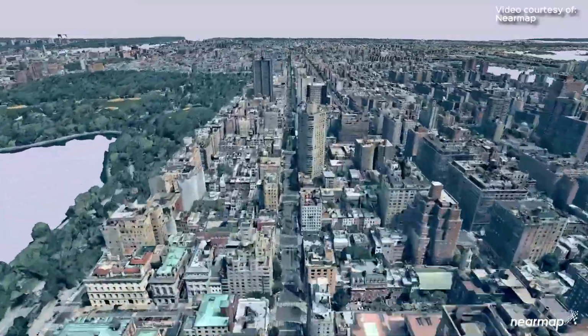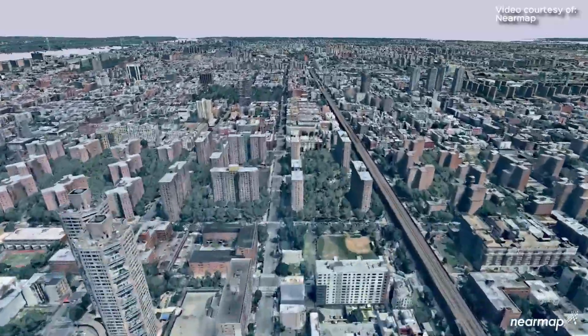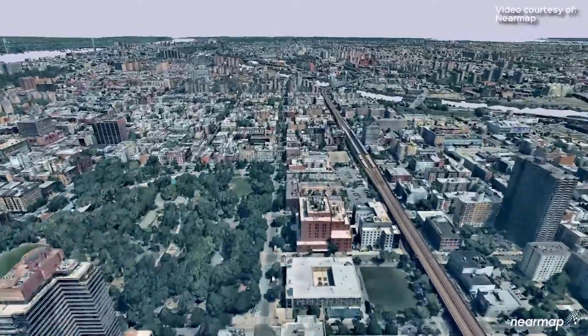But that's not a digital twin in and of itself. That's basically the geometric model. To that, you then have to federate in this other information, both the design data from the history of their design, and the operational data such as from sensor networks, SCADA or IoT, work order histories, inspection histories. These types of data can then be synthesized and fused together with this geometric representation. So you have a really easy to navigate and easy to understand visualization of all this data.